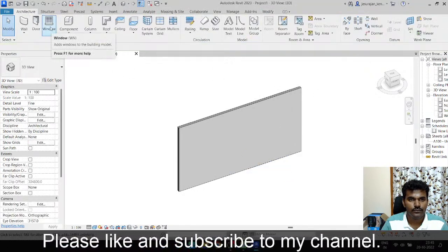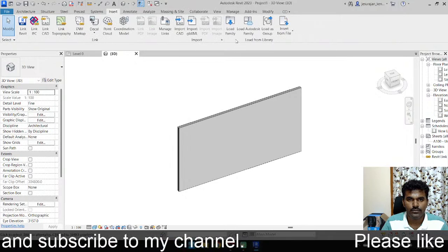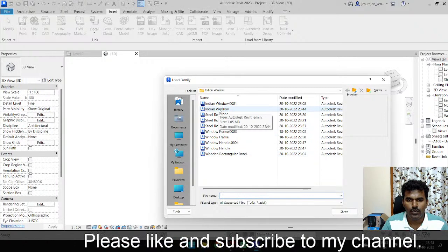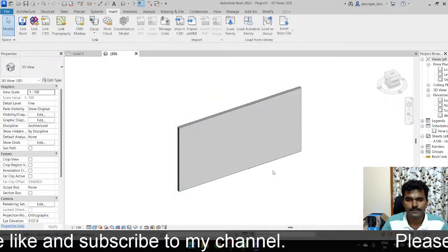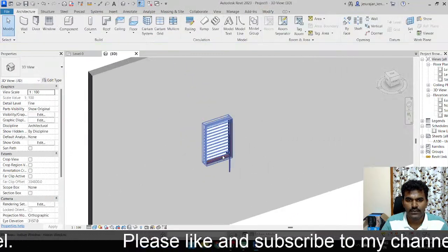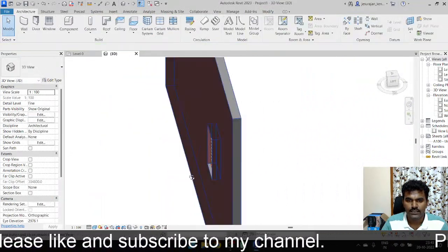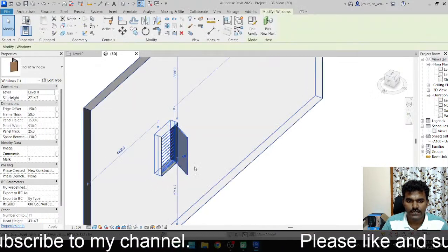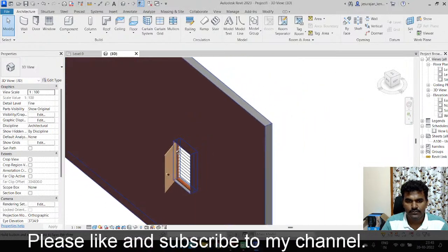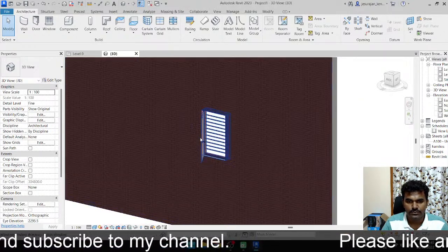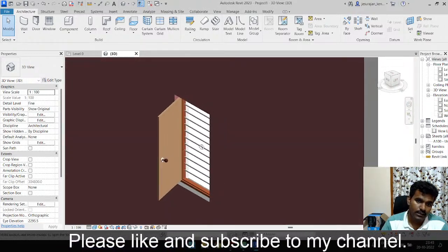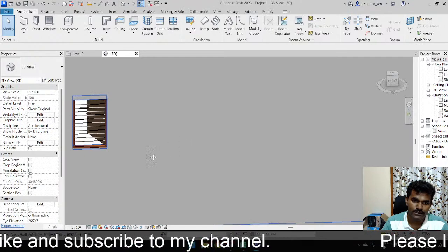And go to window. So before loading the window, load Indian window, open. Go to architecture, take window and just place. Wow, you see here how this looks. Select, spacebar, you can change the direction here. So this is the wooden window with the steel rod. Yeah, I think it works fine.